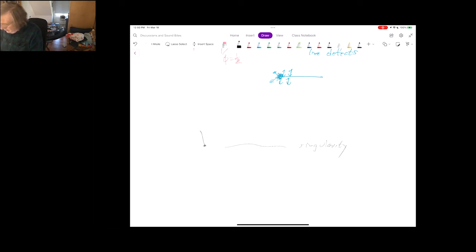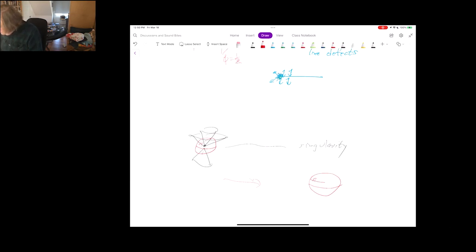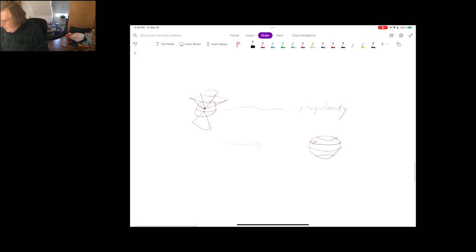like so. It may have a bunch of cones coming off of it. It could be the boring one, which is just concentric spheres. And what you do is you intersect this point with a sphere, like so, and then you look at the sphere. Here's the sphere. And the intersection of all these cones with the sphere is a bunch of circles. Right, so this is the intersection of those 3 cones. And what you then say is that the way that you describe the different defects, or describe the defect structure at this point here, is you look at the pattern of circles on the surface of the sphere.